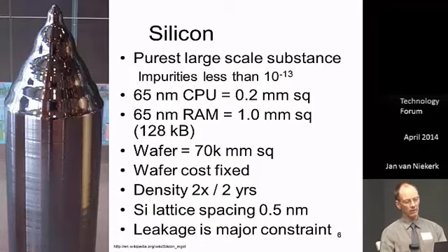And just to make another very important point is that leakage in silicon, as you shrink all these dimensions, is becoming significant. So in your Pentium processor, about half the energy in the Pentium processor is just going to waste and to heat because of the current that's leaking like a sieve through all the gates to the bottom of the chip.